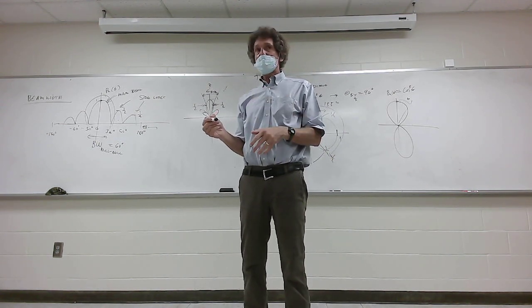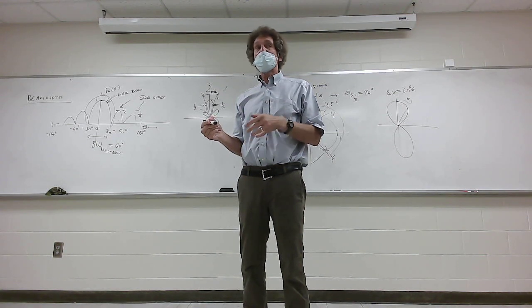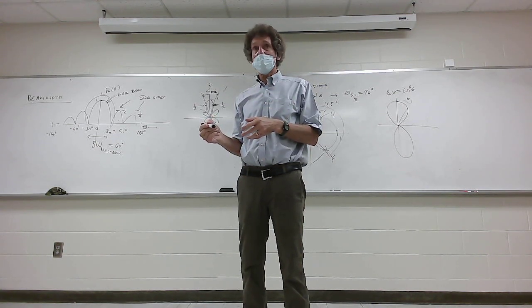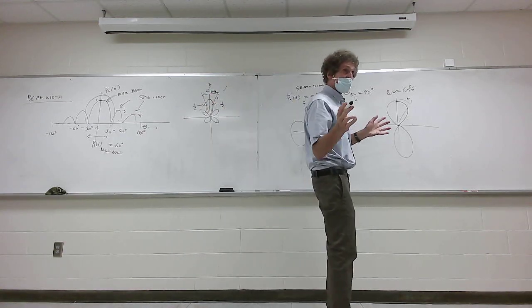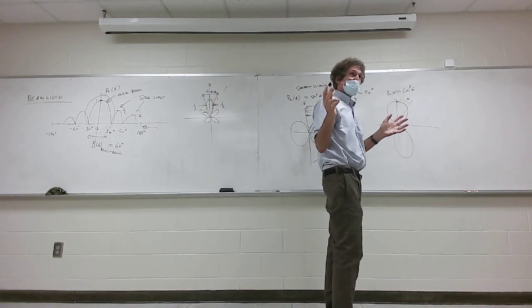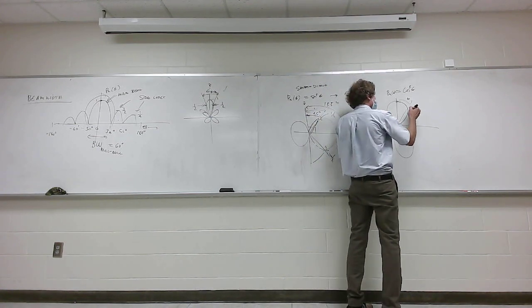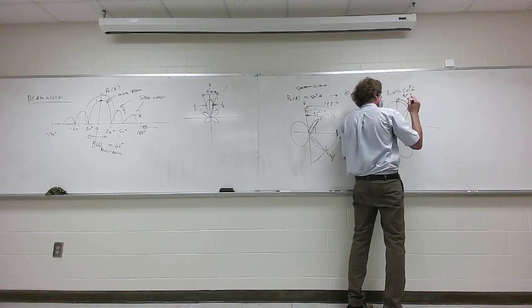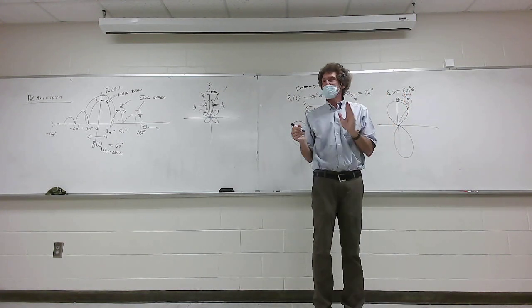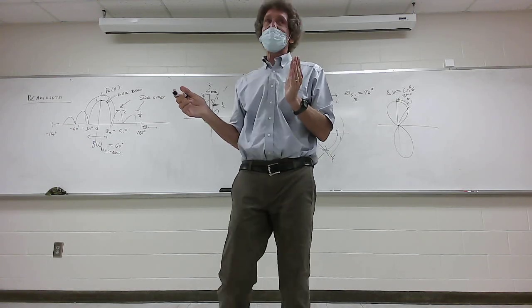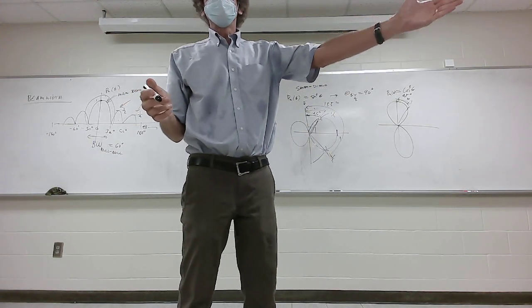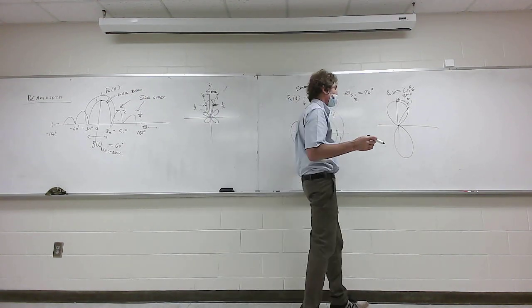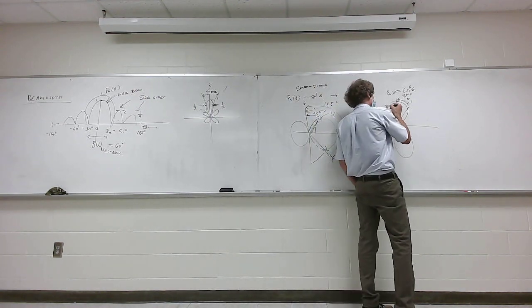So where is cosine squared equal to 1/2? It's where cosine equals 1 over square root of 2, or at, y'all agree, 45 degrees? Everybody's suspicious. Sure, it's 45 degrees, right? That's what it was last time. What's the difference in this one? Yeah, it's not shooting out at 90 degrees, it's at 0 degrees, right? So what's the beam width? It's from here, right, to here.